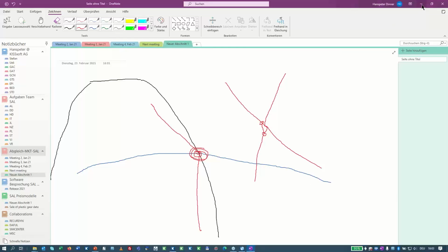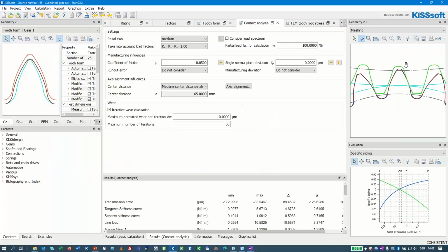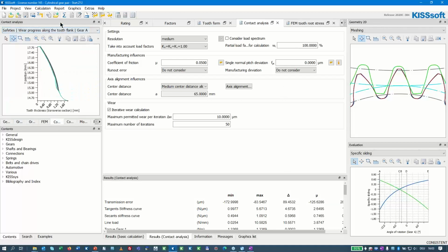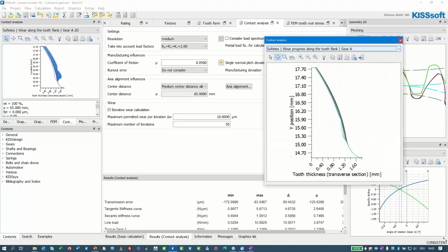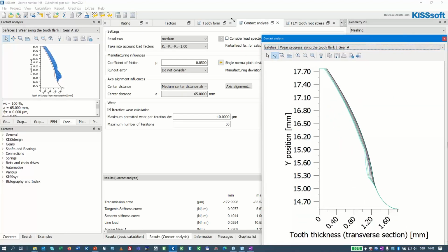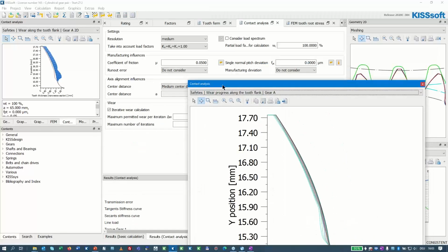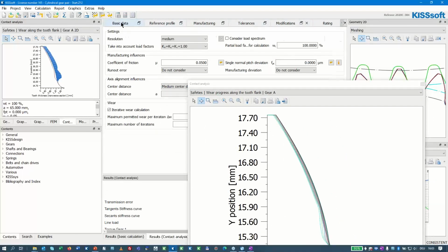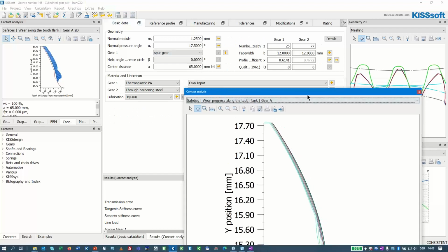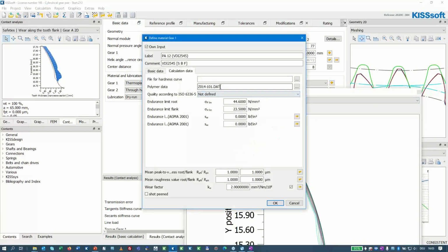Okay, thank you, Hans-Peter. We have received 2 questions that are related directly to material properties of plastic gears, so please excuse me if I don't pose the questions exactly as you did, because I'm combining these 2. How did we get data for SN curves of plastic gears, especially for bending stresses, which we use in the wear calculation? Often there is only data available for root strength, but not for pitting. And combining this with the second question, where do we enter plastic gear data in KISSsoft?